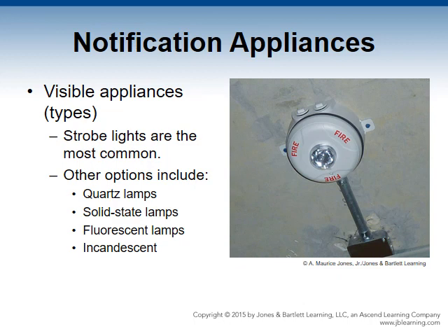Quartz lamps provide a high-intensity light output and are well suited for the outdoors. Solid-state lamps are reliable and found on annunciation panels. Fluorescent lamps illuminate signs or messages when a constant light source is appropriate. They are not used for coded or flashing appliances because they have a low intensity output and do not light immediately. Incandescent lamps are available for coded and non-coded appliances, but burn out quickly and require more frequent replacement than any other kind.